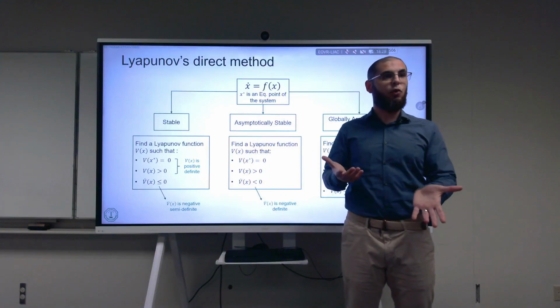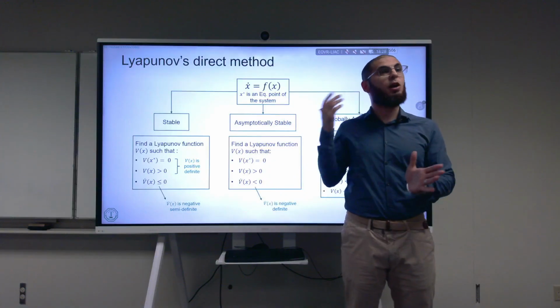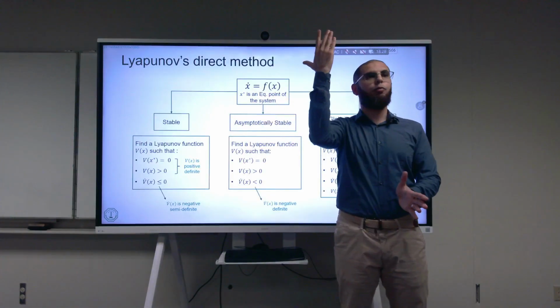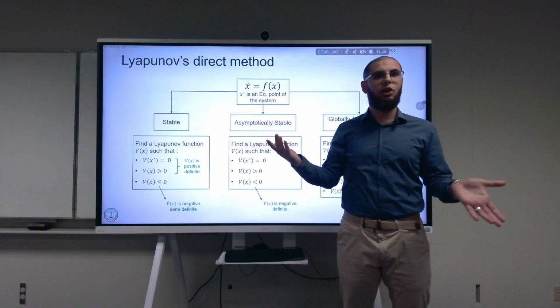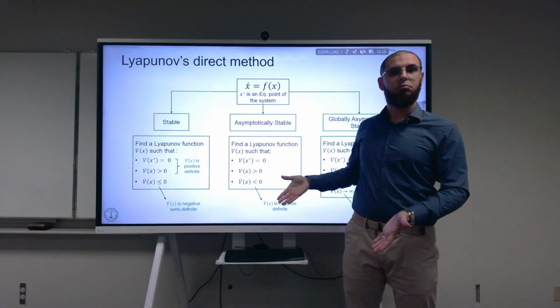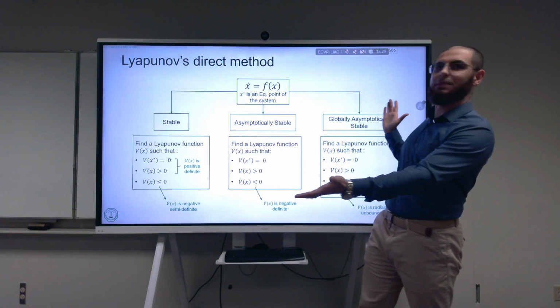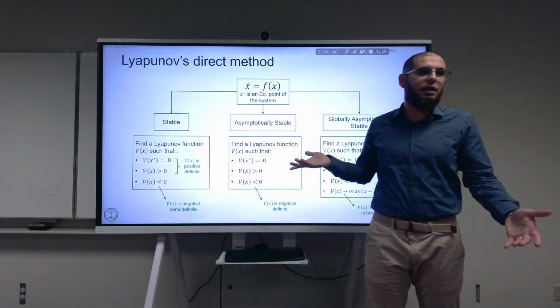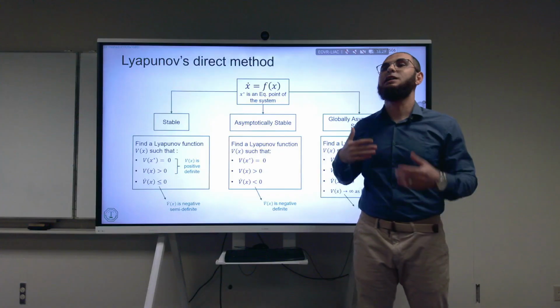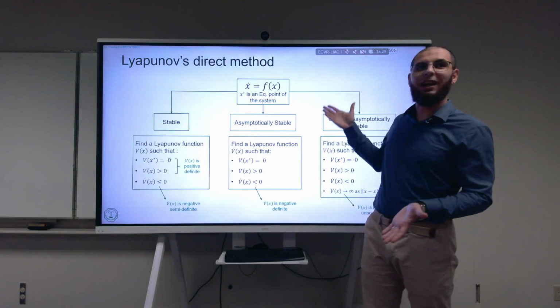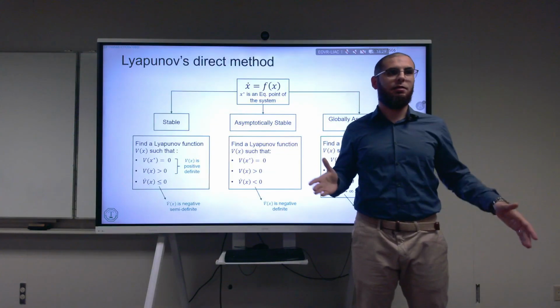And then I take the same Lyapunov function, and I plug in the top equilibrium point, and I find that I cannot do anything here. I don't even have a recipe for instability, so I cannot say. I can't even find the function. There is no recipe. Lyapunov's direct method is only for stability, not for instability.